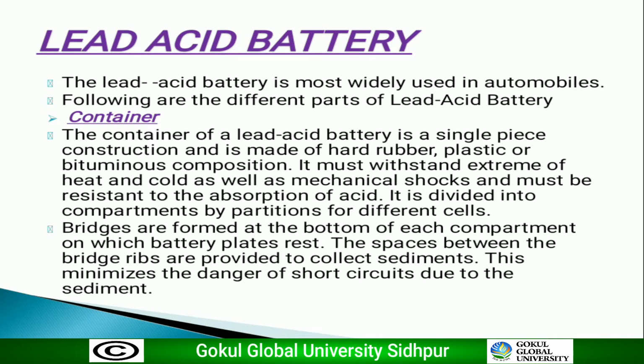Lead acid battery. The lead acid battery is most widely used in automobiles, as I said, and following are the different parts of the lead acid battery which I will discuss in detail. So first of all, the container. The container of a lead acid battery is a single piece construction and is made of hard rubber.